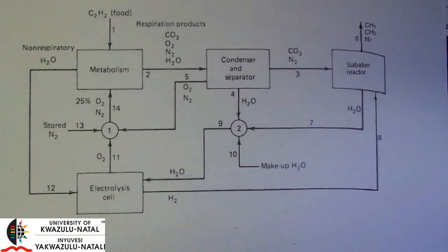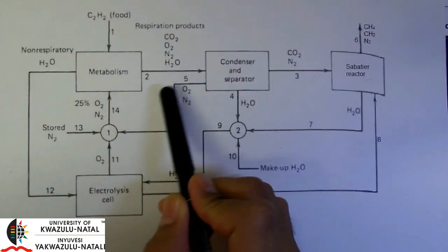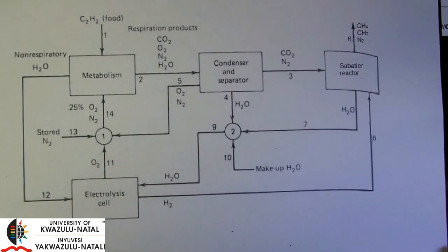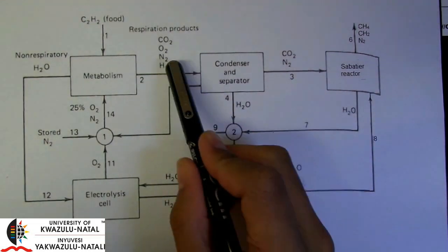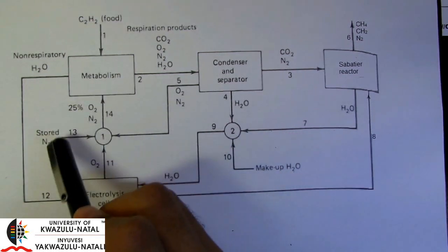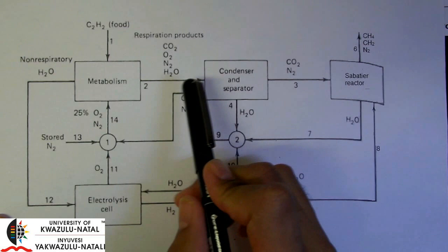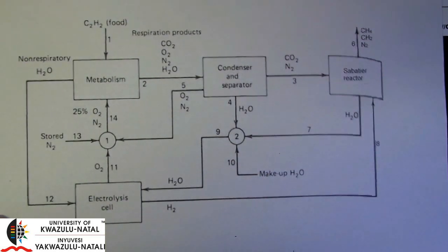The second reason is that a good understanding of mass balances can save us lots of money potentially. Okay, for each stream, we would like to know what the flow rate and composition of each component is in each stream. Now, an amateur's approach would be to simply install a flow meter in every single stream. And remember, these physically resemble pipes. So installing a flow meter in every single pipe will be very expensive.